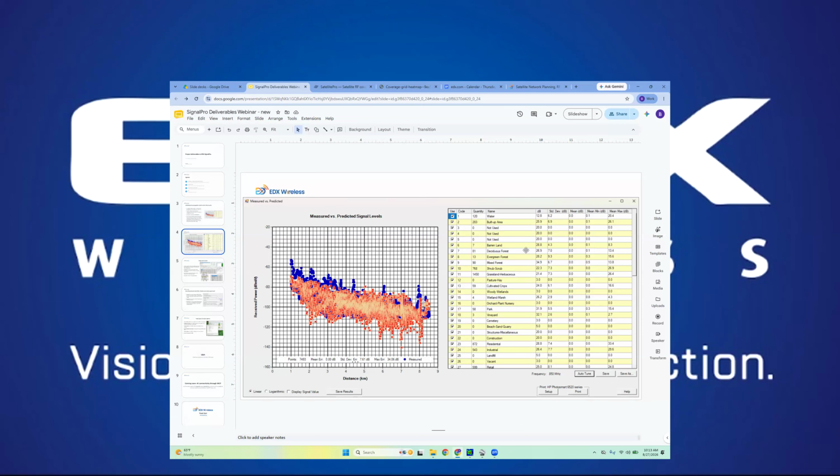And for this measurement file, we've adjusted the clutter losses, which you notice with this auto tune function here. If you're using that methodology of a terrain model plus clutter, this auto tune will automatically seek the best clutter loss values to fit your field measurement data.